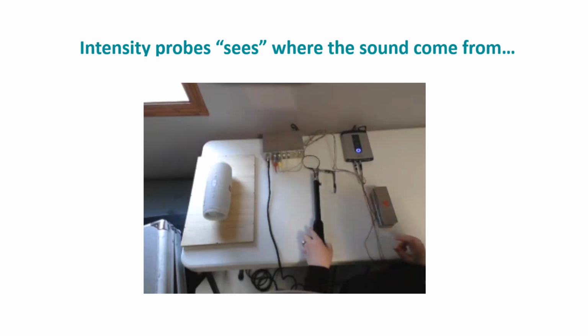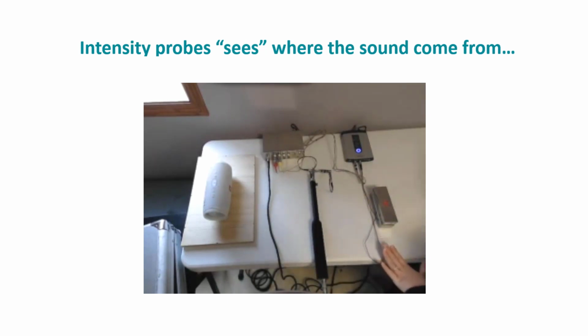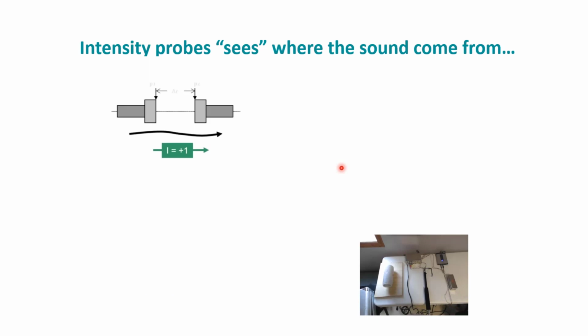There are reasons we use different spacers, and reasons we use 2 different microphones. These are phase matched microphones because we are trying to measure the speed of the wave. We're trying to figure out how fast the wave is going so we can get that magnitude and direction, the direction being the important part. So we use 2 microphones facing toward each other, phase matched. We can tell the time difference between when a sound wave hits one microphone and when it hits the other, and then the software can back calculate that. There's a space in between because it has to relate to frequency.